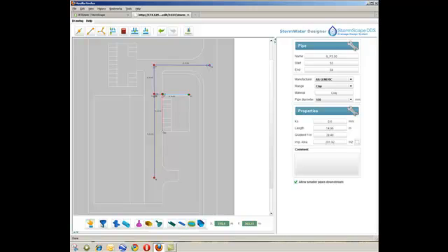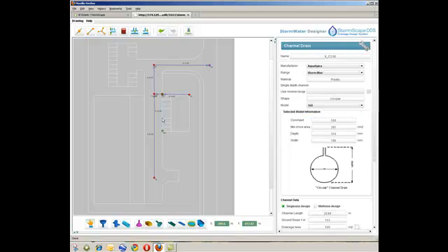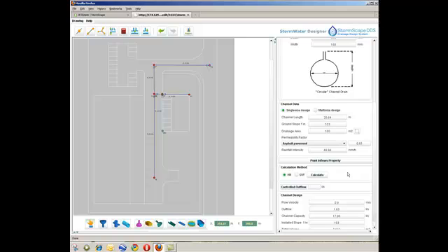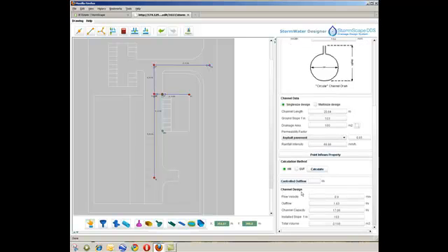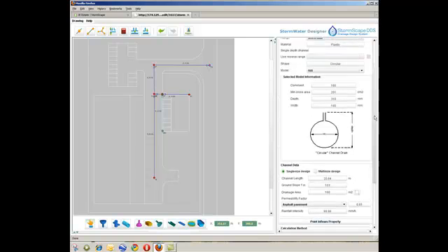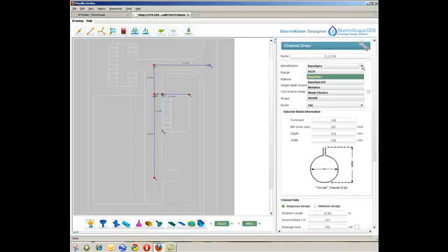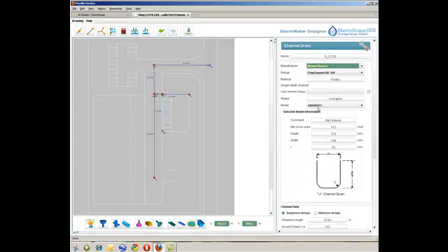The channel drain entered in the system has been selected. The associated data appears within the panel on the right side of the design window. Within this panel, the information included relates to channel data, calculation method, and channel design properties. From the established database, StormScape allows the user to browse and select a particular manufacturer, and in this case, a Wavin Polychannel 100 SK021 has been selected.